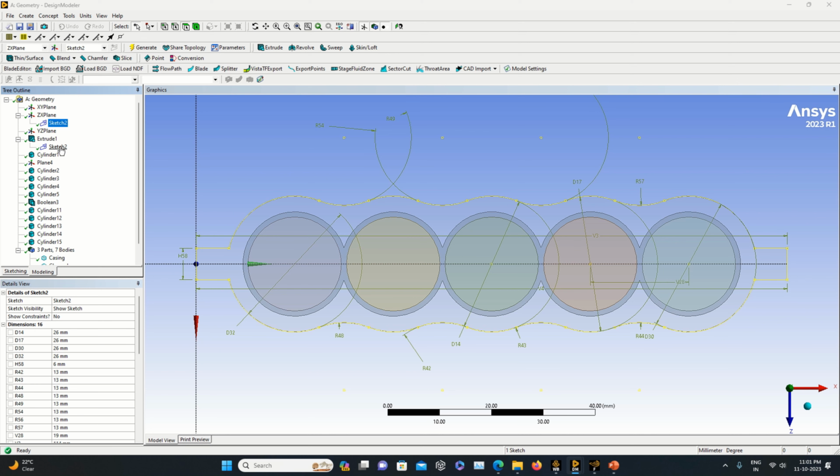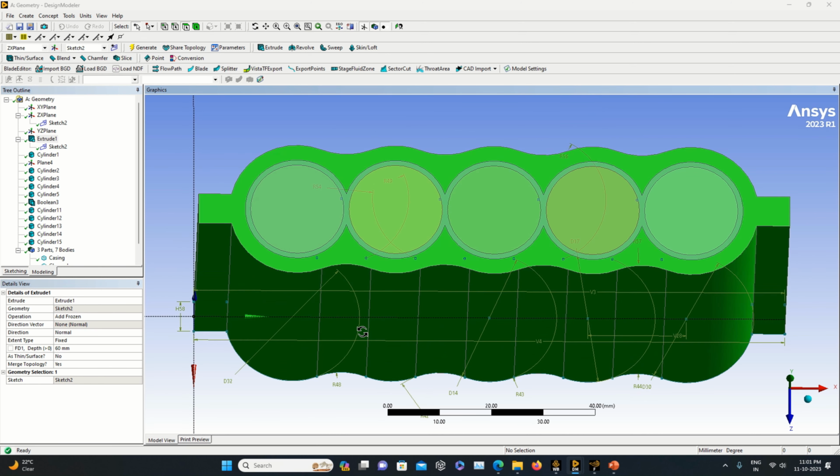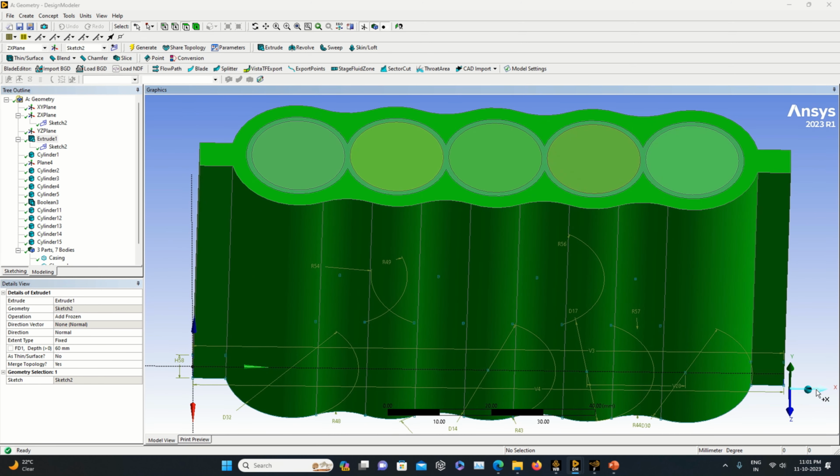Okay, so next, the extrude operation has been done. So you have extended this object in the positive direction of y as per the dimension which we had. Now what has been done is we had tried to introduce one cylinder. Which is this cylinder over here? The cylinder which you are observing right now, if you see the radius over here is 10, so the diameter will be equal to 20. If you know the diameter of a lithium ion cell, it is around 18 mm, and here it is 20.